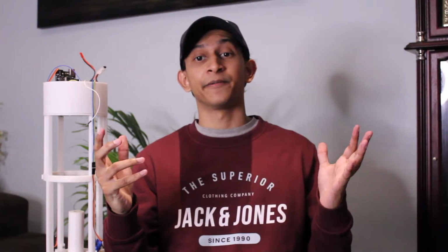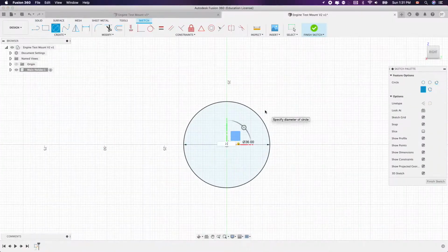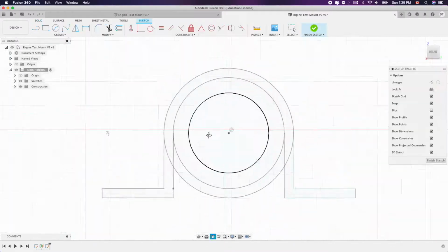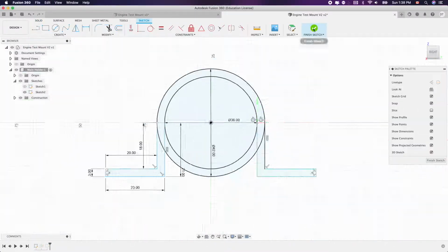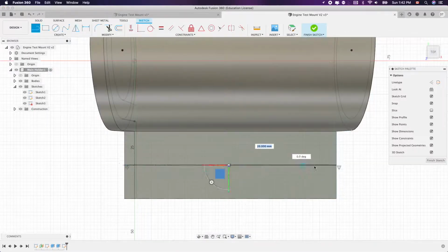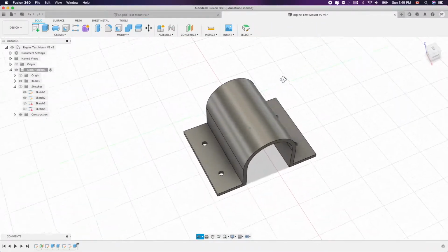So for the rocket engine, I decided to use the C63 solid rocket motors. They generate about 15 newtons of thrust and have a burn time of 2 seconds. Prior to this project, I had never used a rocket motor, so I thought the best way to test this engine was to do a static fire. To do this, I designed the engine mount that holds down the motor in one place. It was a quick and easy design, so here's how that turned out.